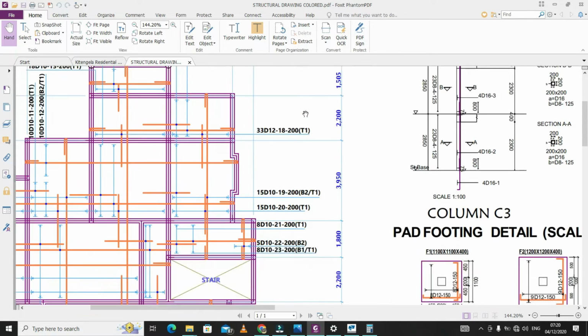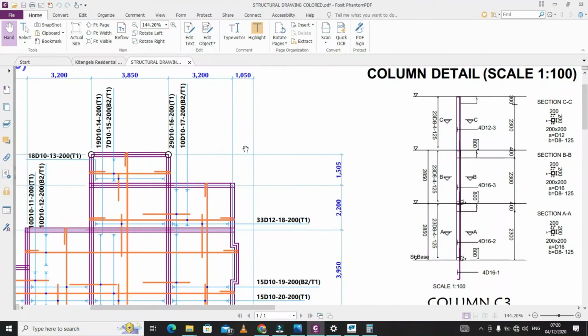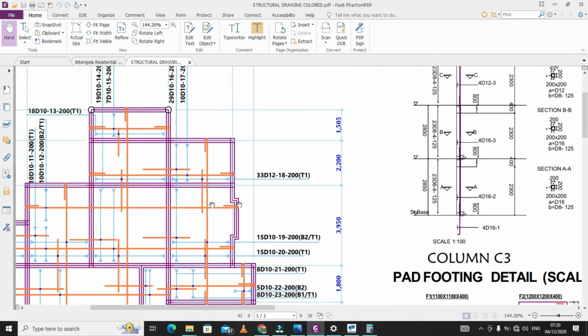Whether it's one-way or two-way also affects how the loads are going to be distributed when you draw the yield lines for the slabs. I shall not get into that right now. Those two are what guide whether a slab is two-way or one-way. So you just keep that in mind.